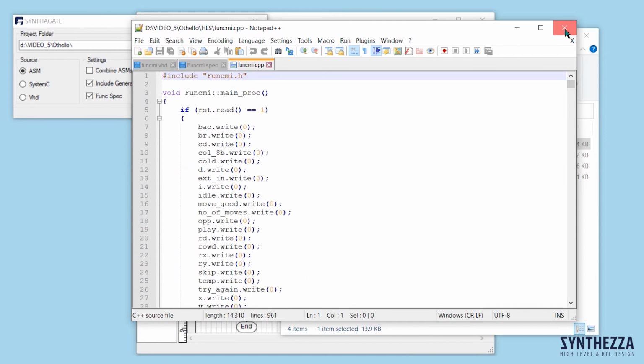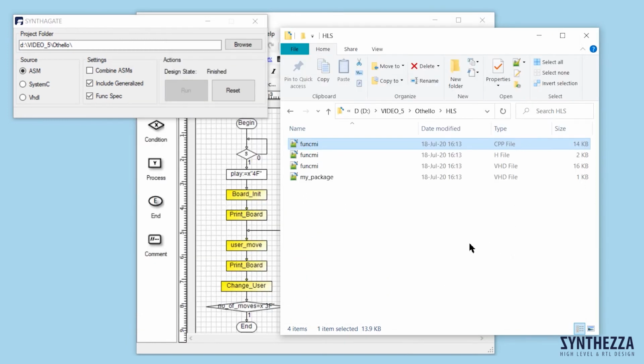After preparing a test bench, the designer can simulate the functional project with any simulation tool. The designer must choose what they would like to use at the simulation at the high level, version in VHDL or version in SystemC. The same test bench can be used at the last stage of the design at the RTL level. I will return to this simulation a bit later.